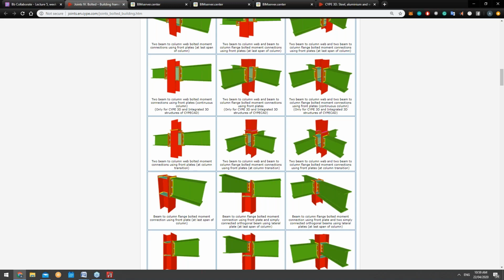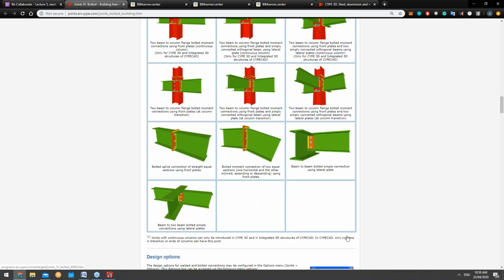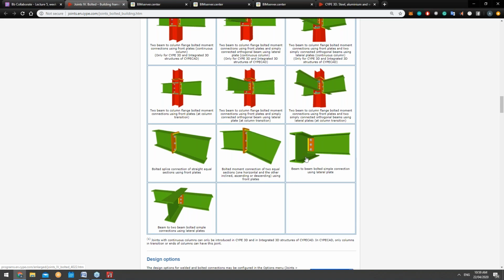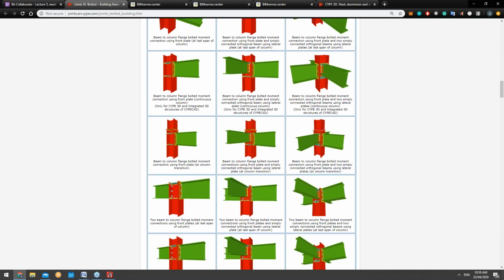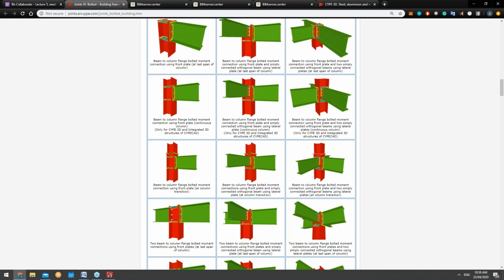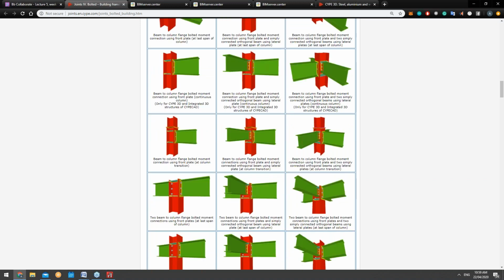Now there is a question on tubular connections as well. So we do tubular connections. Those aren't shown here, but as I said in the question prior, for our tube or boxing connections, you can replace all these joints with any simple section, and we can do them. So not only I-beams. This is what I want to get completely across, that we don't only do I-beams. They are simple sections, but for any simple section, as long as they all belong to the same family of those elements. So let's move on.